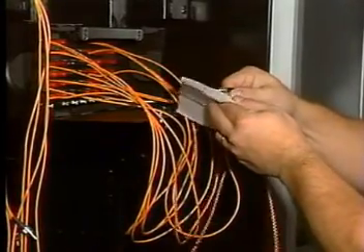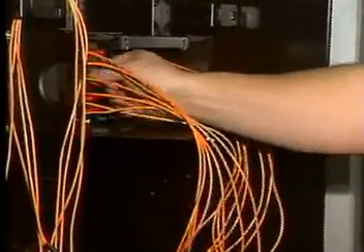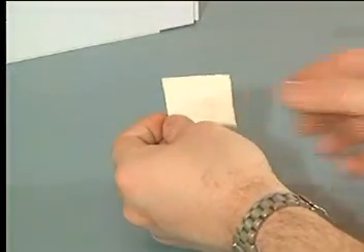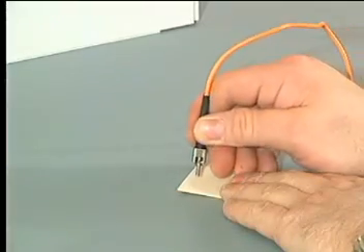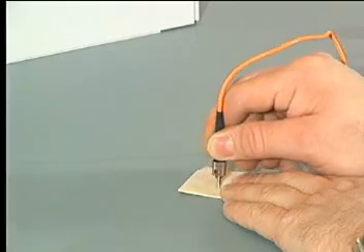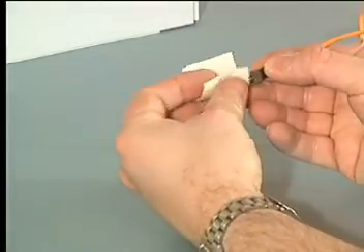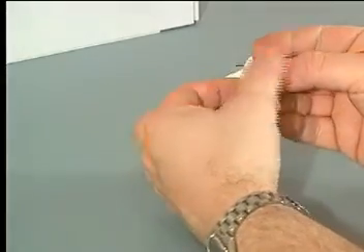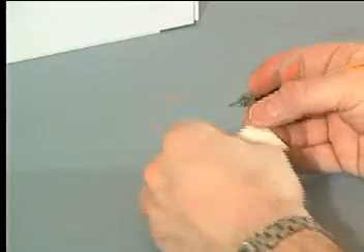Alcohol-based products are inexpensive, easy to use, and have been used for decades to provide acceptable results in low-speed multi-mode systems with LED sources. First, fold the pad over to form a small cushion. Hold the connector vertically as shown here, and lightly wipe the ferrule end face over the optic pad. Repeat this several times, being sure to use a fresh section of pad for each pass. Then, use the pad to clean the sides of the ferrule. This removes particles along the ferrule sides to improve mating alignment and to prevent contaminants from being pushed into the connector.